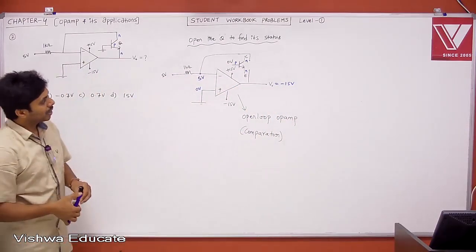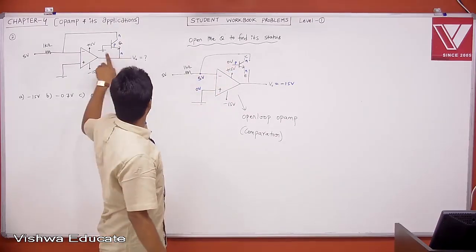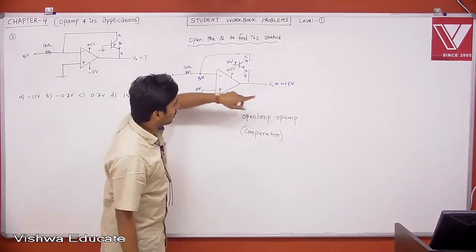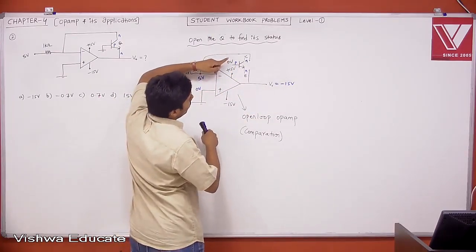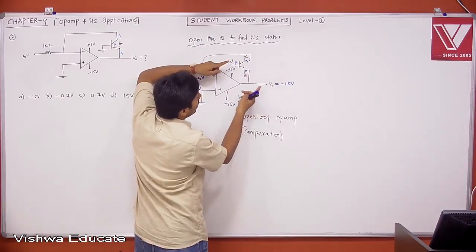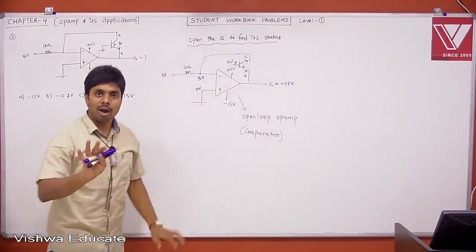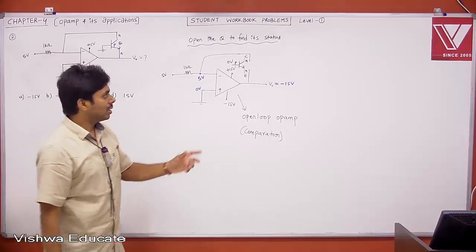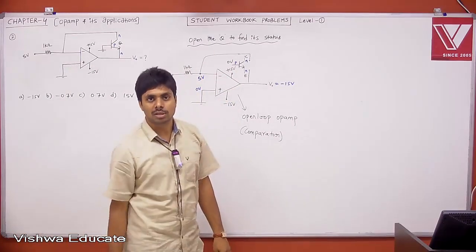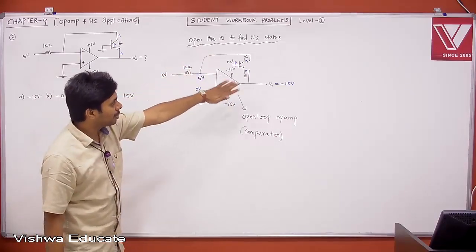Therefore, now tell me, if transistor is opened, then the transistor base is connected to 0 and the transistor emitter is connected to minus 15. Therefore, P is connected to 0, but don't think that it is off. I told you, right? We have to see other terminal. If the other terminal is having negative voltage, therefore now 0 minus 15, your PN junction diode can conduct. It needs only 0.7, but it is having more than 0.7. Therefore, whatever it needs, it will take. Remaining voltage will be given to some other circuitry. Or op amp will not give that much. But if you have open circuit a transistor, your output will be minus 15.